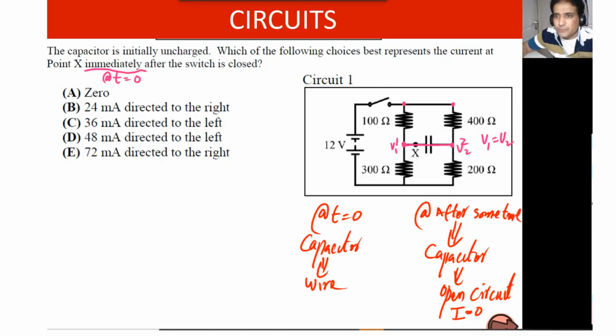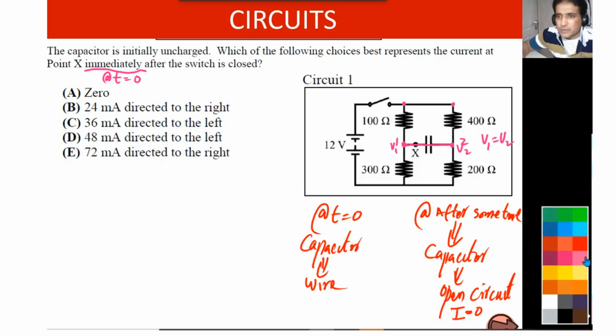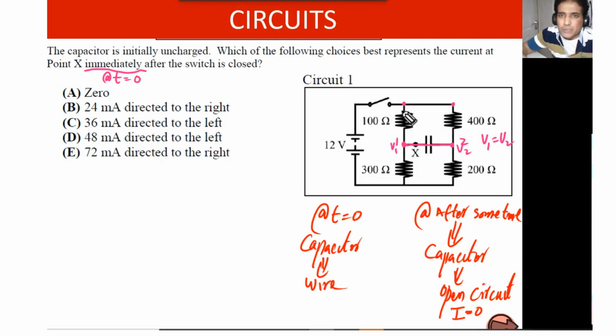So how can we find out how much voltage is dropped? For that purpose, you need to understand, if I have these two, can we draw like this? You see, voltage across this one is equal to voltage across this. Can we say these two resistors are connected in parallel? Another way to draw is like this. This is just a wire. I can just draw like this. Okay, so these two are in parallel.